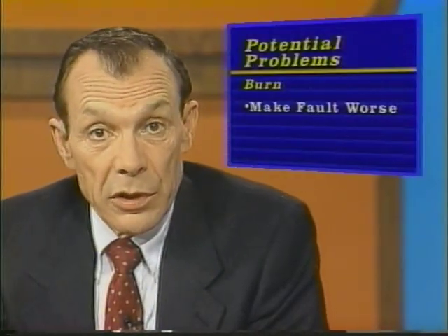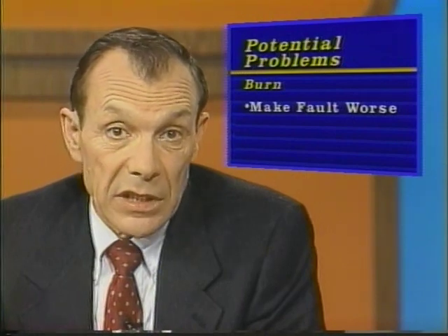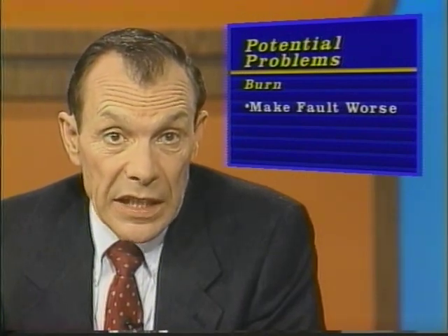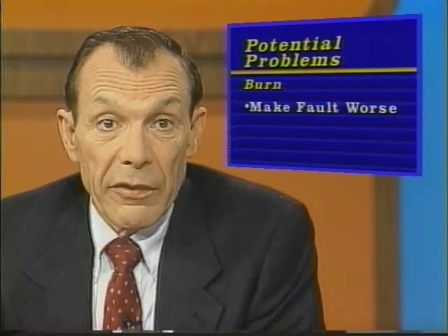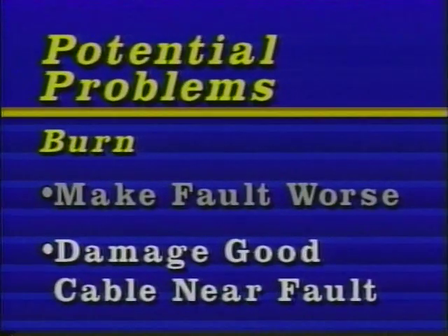If the entire area of the insulation damage is not removed when the repair is made, you will have another fault very soon. Some people do not like to burn a fault unless they have to, because the heat generated during the burn could make the fault worse. If the conductor melts into a dead short contact with the neutral, you'll have a fault that's very hard to locate. To burn a dead short open can take a long time and do serious damage to a good portion of the cable near the fault.